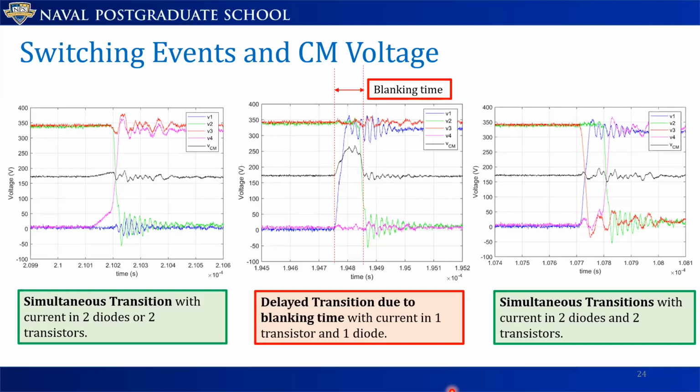Okay. So the follow-up question on the PDM is, is the PDM done with hard switching? And if so, would the simultaneous turn-off of multiple legs increase the turn-off transient voltage spike? Yes, it's done with hard switching. And the pictures on the screen right now are the experimental measurements for switching with PDM and silicon carbide devices. I'm not sure if this answers the question.